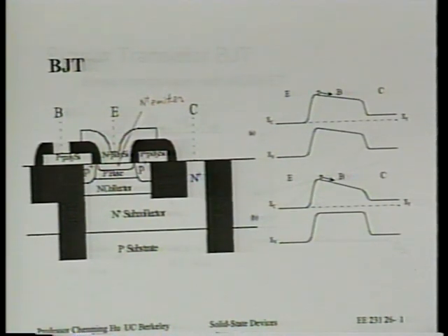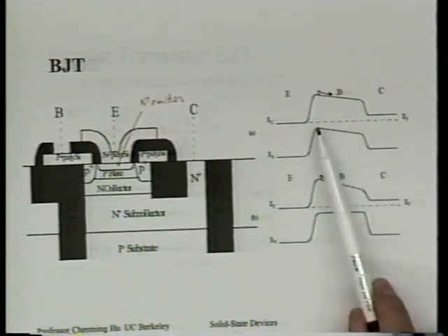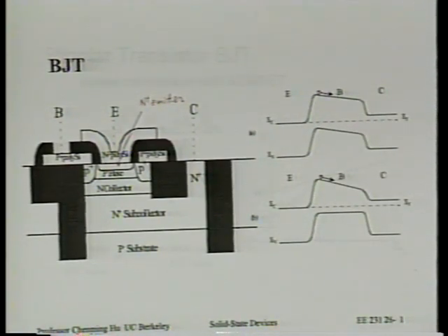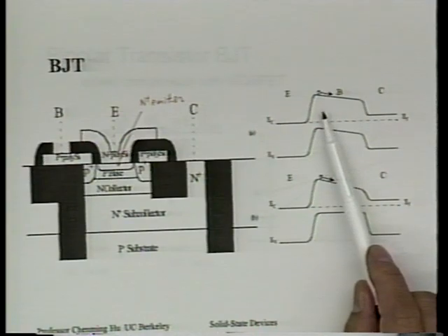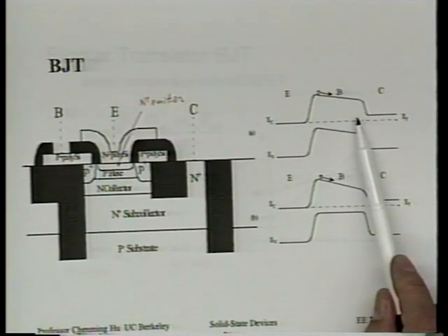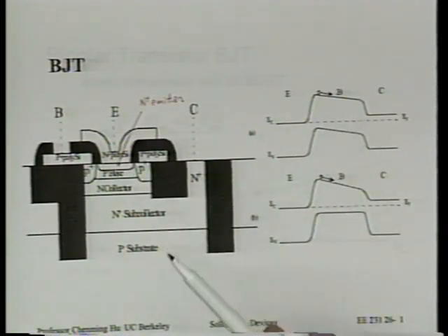All right? Okay. Just in case you recall from somewhere before that, we could do the same thing just by changing the doping gradient in the base, right? This is probably what you heard. This doesn't work well for several reasons. I'll just give you one simple reason. In order to do this, you have to dope the emitter side of the base heavy and dope the collector side of the base light, right?